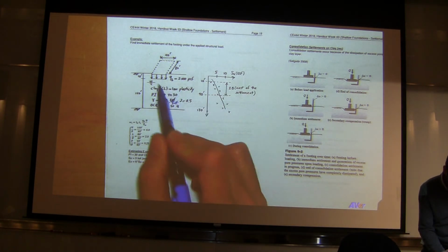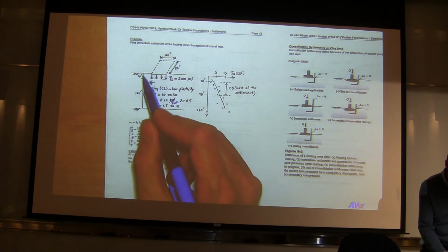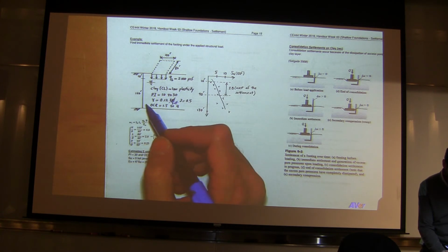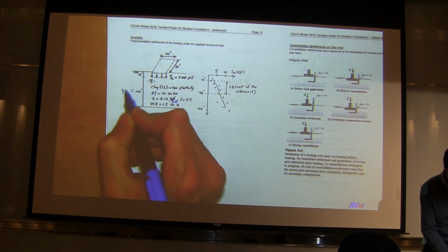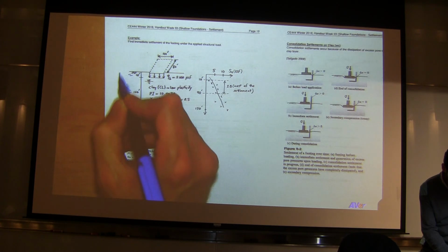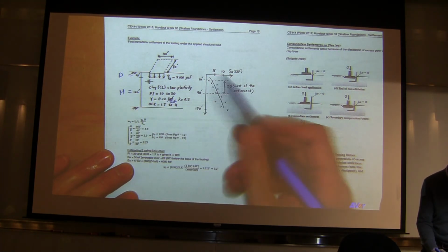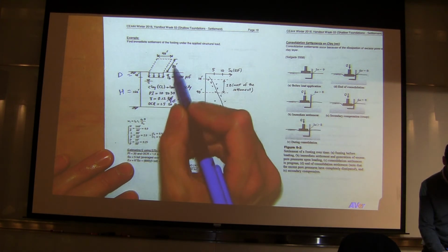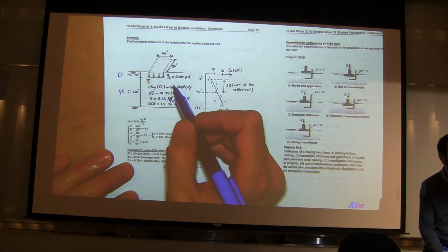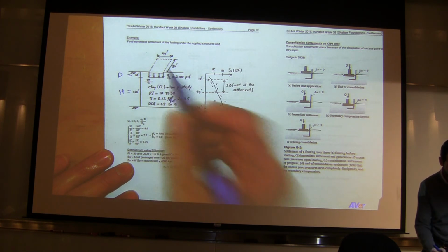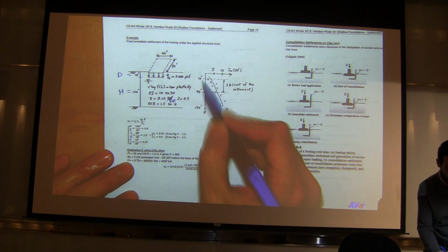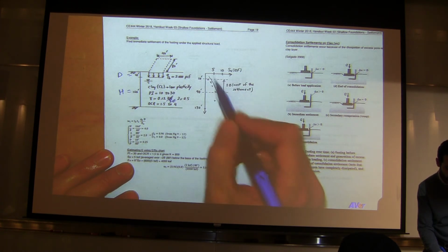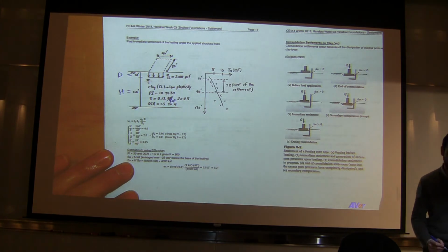You see here, the embedment is 10 feet, and then you have 160 feet of clay. So this is going to be your H, this is going to be your D. And to average SU, we are going 2 times B. So B is between 40 and 80. Which one is B? 40. So 2 times 40, that's 80. So I'm going from 80 feet below, so 10 to 90. And I average these, and you look at these values, it's almost 5 KSF, roughly.